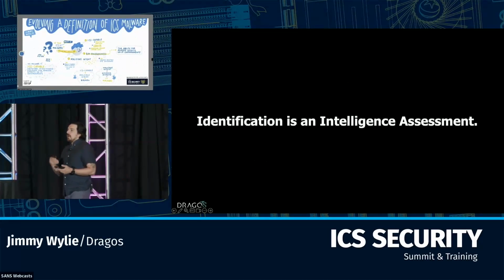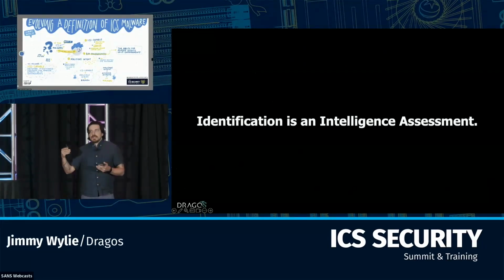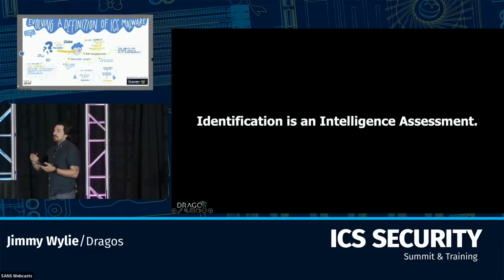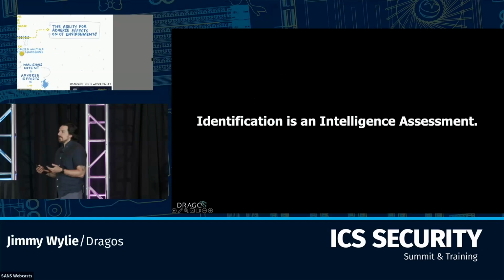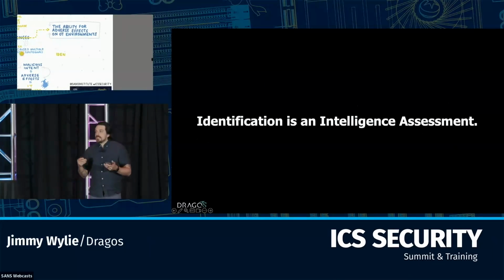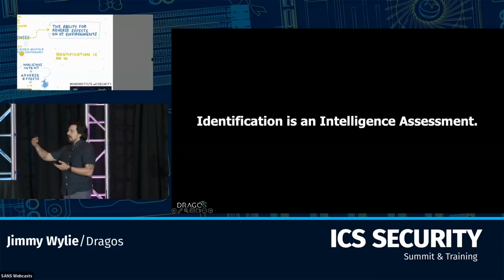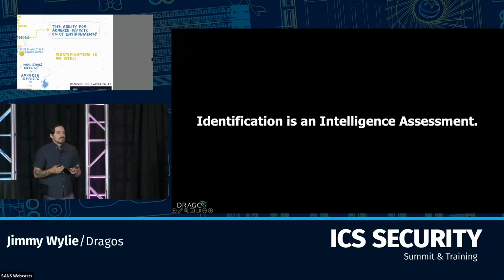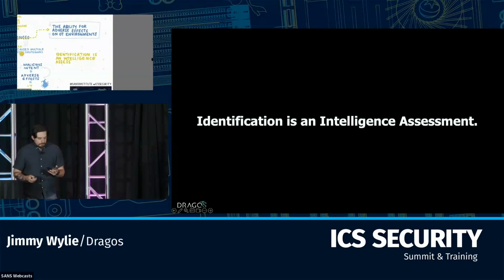And what that means is just because we call something or we decide that something isn't ICS malware today, doesn't mean it's not going to be ICS malware in the future, right? In the face of evidence, potential ICS malware could become real ICS malware if we get more evidence of intent. And the same thing happened with FrostyGoop. We sat on FrostyGoop for a while because it just looked like a Modbus tool. And we weren't sure whether or not this was malware. Then we got the evidence of some of the testing against the ENCO controller. We found some other versions of it. And then we got evidence from the security service linking it. And we were like, oh shit, this is actual ICS malware. We should do something about it.